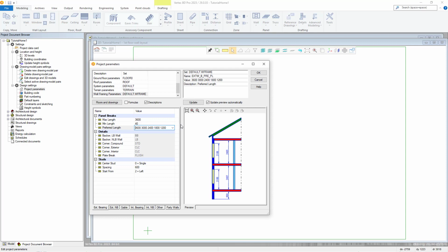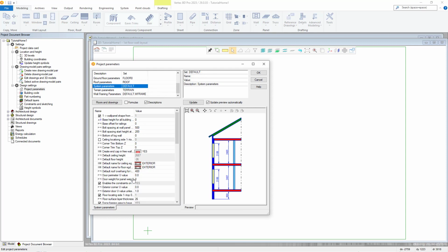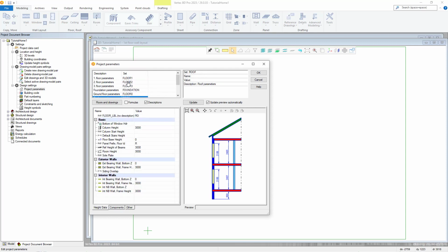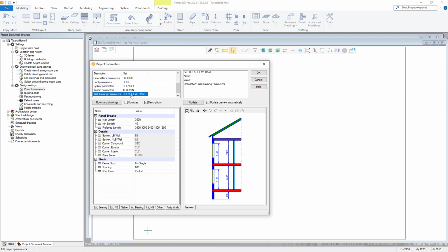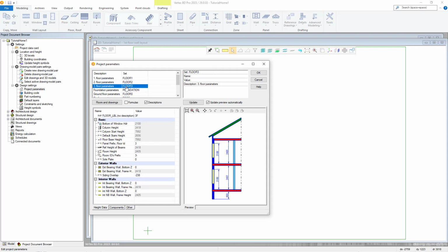You can set different values of these framing preferences for the various wall types by selecting the tabs along the bottom and for each level of the building. The default wall libraries only include exterior bearing, interior bearing, and interior non-bearing walls, so we don't have to worry about the other tabs at this point. When finished, click OK and save again with Ctrl S or the File menu.